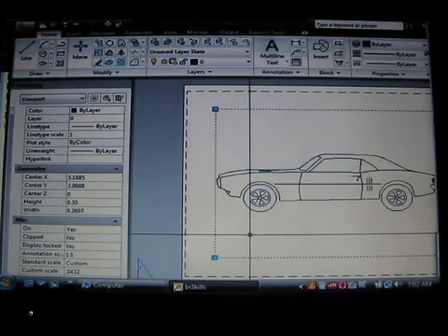One of the biggest benefits to annotating in paper space is that you can create multiple viewports in one tab. In model space, you only get one shot at making your drawing. You can only have one view. Many drawings need more than one view of the object to create a drawing, so you can get more done with paper space than you can model space.